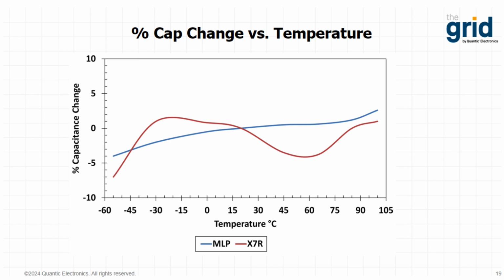One continuing theme you will see in this presentation with film capacitors is that they're generally quite stable. This is loosely related to the low dielectric constant referenced earlier, the 1000x seen in ceramic versus the orders of 2 to 3 of K value seen in films, right? So that causes us to be very stable.